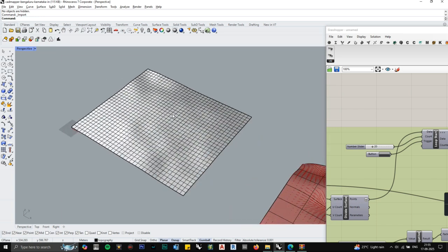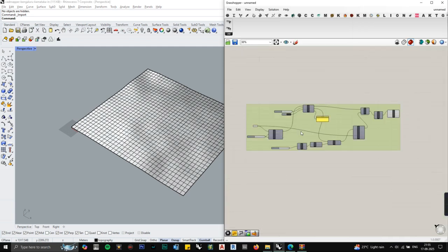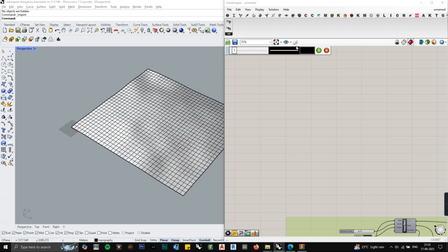And before we jump into Grasshopper, let's look at the actual logic that we're gonna use to define those drainage lines. So if I have a section of a contour or a sloped surface, I'm going to extract some points on this surface. After that, I'm going to move those points downwards, let's say by 1 meter each.